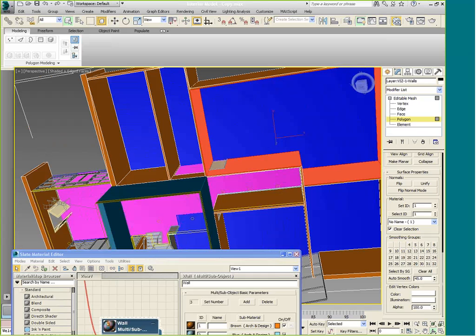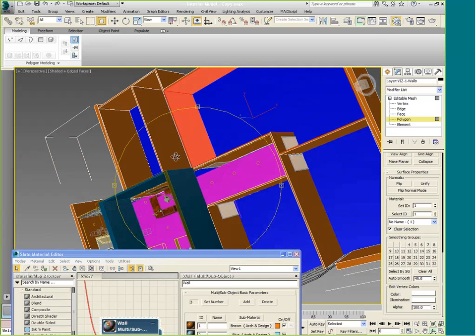And this one right here, and there's one more wall pending, and this one right here. We need not go back into the Slate Material Editor; in the command panel's material section, we just enter 2. So set ID as 2 and hit Enter, and if you click outside somewhere, you will notice that material ID 2, the blue material, has been assigned to boardroom number 1.